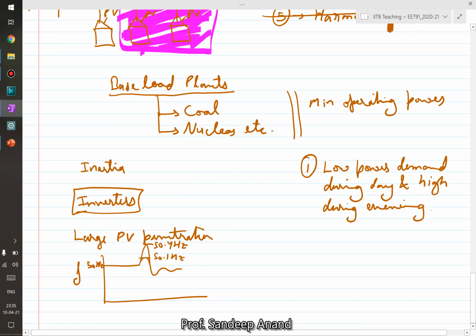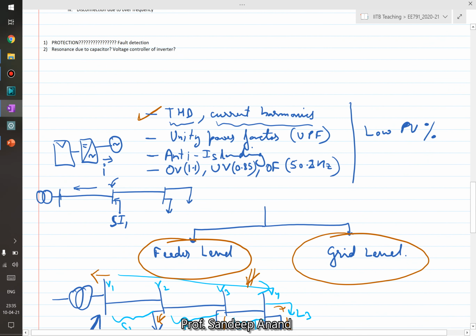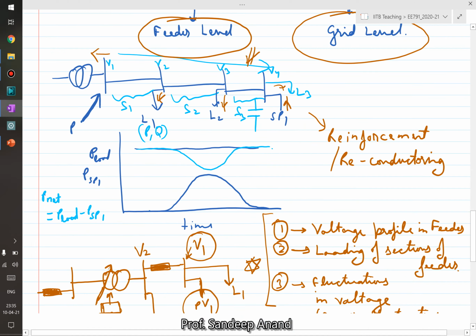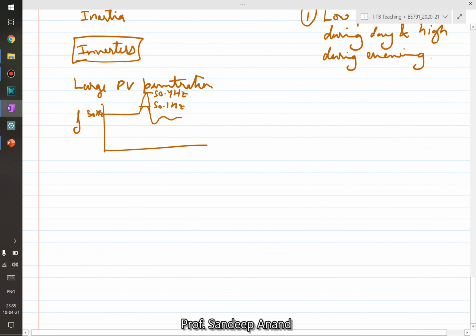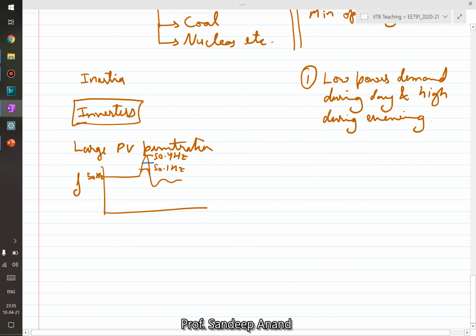And now if you see the previous discussion, we have asked the inverters to get disconnected as soon as the frequency goes above, let's say, 50.2 or 50.3 Hertz, over frequency. So what will happen now if these two systems get separated? The frequency goes up. This is the point where the inverter gets disconnected.